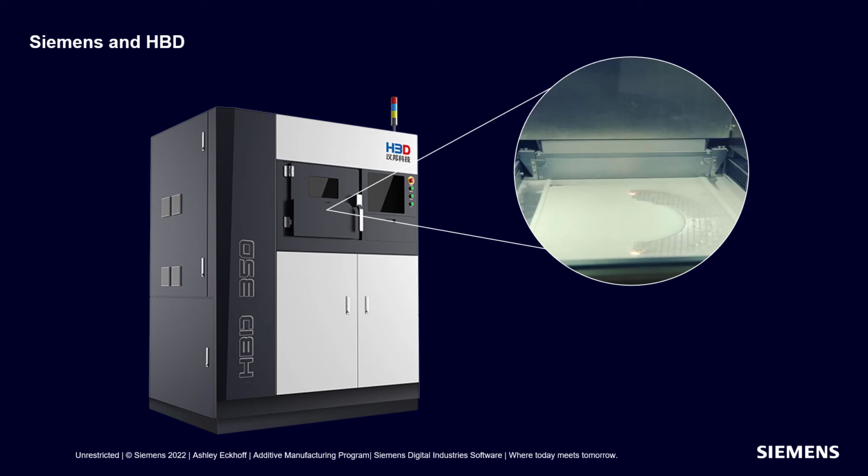So now that we've seen the basics of the workflow for design, simulation, and printing of molds with conformal cooling in NX, I'd like to talk briefly about our partnership with HBD. You may have noticed during the demonstration video that we do interface directly with HBD hardware. Once your printer build processor is installed, you can select the HBD printers you have installed from the drop-down, and then set the printer build options all from within NX. The printer code is generated and can be sent directly to the HBD printer so that you never have to use any external files or file conversions.